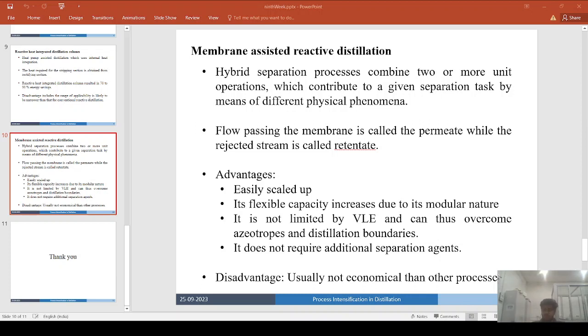Now, what is the mechanism of the microwave assisted reactive distillation? When a microwave field is applied, dielectric heating takes place that differs in mechanism from conventional heating. During conventional heating, the highest temperatures are reached at the surface of a vessel, where bubbles can form and thus boiling occurs. In contrast, dielectric heating gives rise to an inverted temperature gradient because of volumetric heating, where the energy is dissipated over the entire volume.